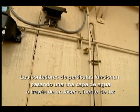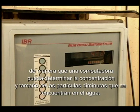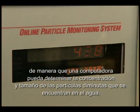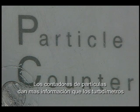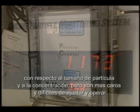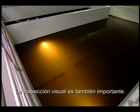Particle counters operate by passing a fine stream of water through a laser or light source so a computer can determine the size and concentration of minute particles in the water. Particle counters give more information than turbidimeters regarding particle size and concentration, but are more expensive and more difficult to adjust and operate. Visual inspection is also important.